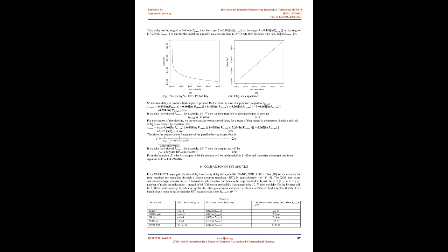At first, we have found out the area/element numbers, switching delay, and switching energy consumption for the individual linear threshold gates, using the same methodology as adopted for the Boolean gates. Next, we have calculated the same parameters for bigger and more complex circuits, and these are presented in Table 2.